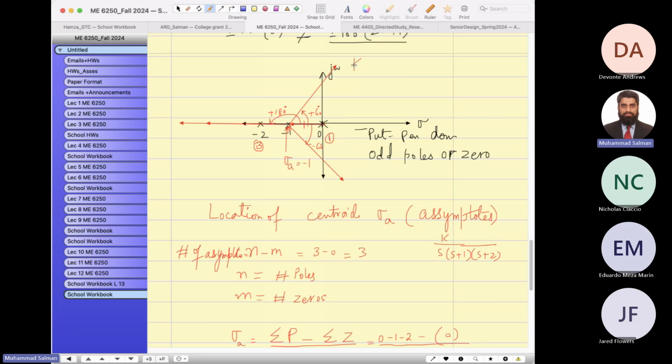When the gain goes to infinity, the poles reach the open loop zeros. And now you will see there is an imaginary line. As soon as the poles move into the right half plane, then e to the plus st, if the value of s is positive, the system behavior becomes exponentially growing and unstable.